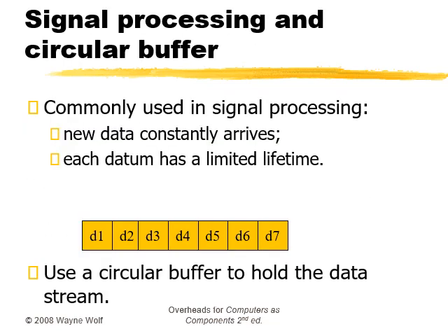In this slide we are going to talk about signal processing and circular buffers. The circular buffer is a data structure that lets us handle streaming data in an efficient way. At each point in time, the algorithm needs a subset of the data stream, so it forms a window into the stream. Now the window slides with time as we throw out old values no longer needed and add new values. So the window just acts like a slide.